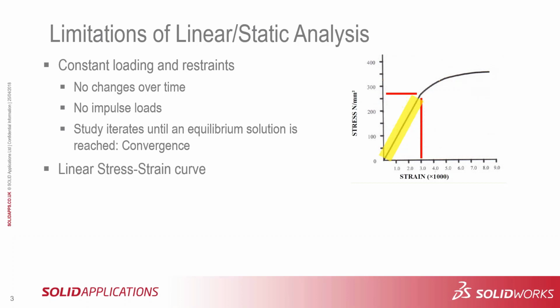And until it deforms plastically, meaning until it deforms to where it won't come back to its original shape, or bends, as we say, or breaks, it displaces in a linear curve, meaning it'll come back to its original shape, and the strain and the stress have a linear relationship, as you can see highlighted in the yellow area. Now we don't go with linear static analysis into this realm. Now the simulation tool will analyze along that straight line as if a material were linear, but we need to know if we exceed yield, we're not getting the result that reflects what the actual curve will be in the